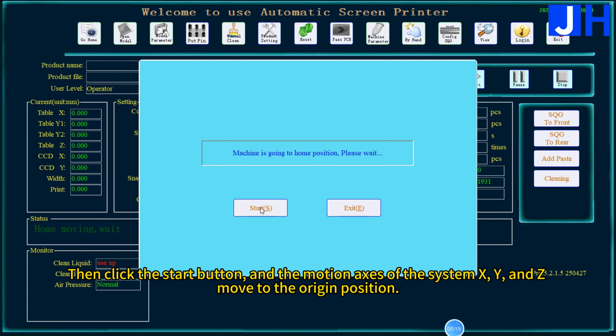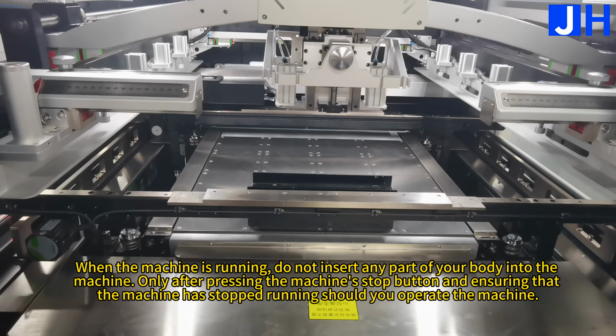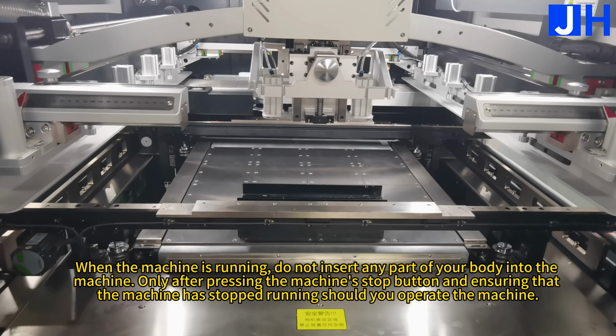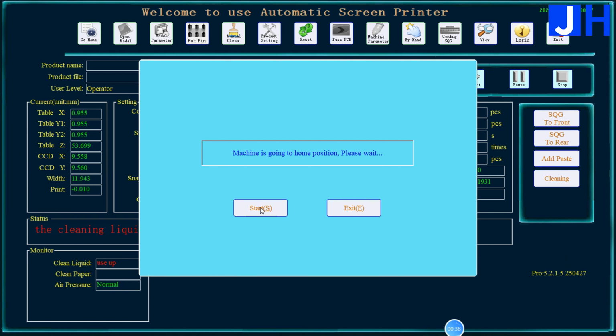position. When the machine is running, do not insert any part of your body into the machine. Only after pressing the machine stop button and ensuring that the machine has stopped running should you operate the machine. Now every axis of motion is moving.